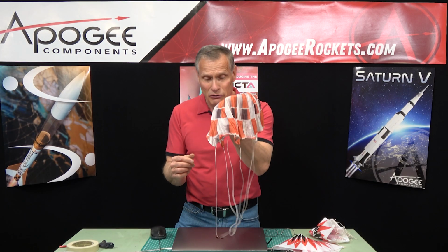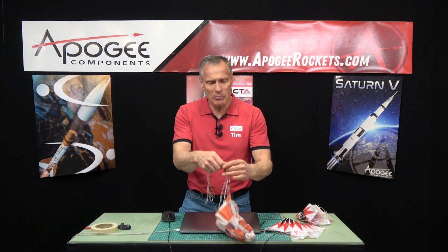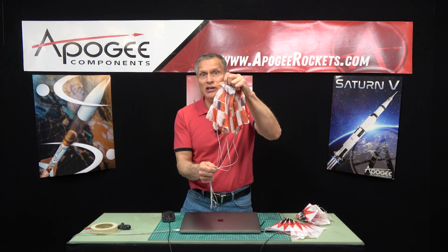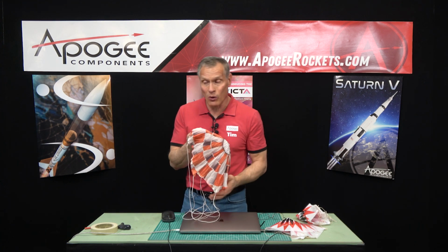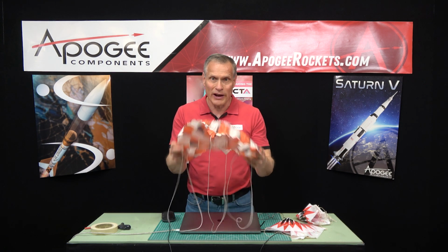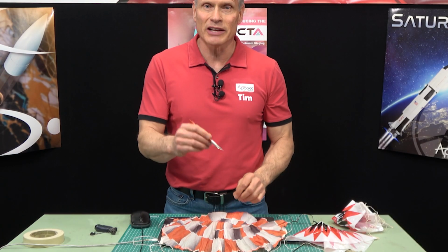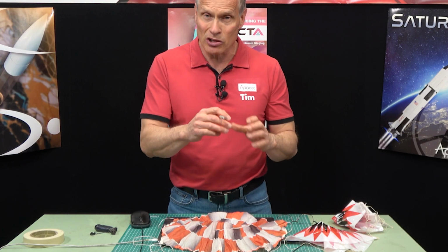You don't typically want to cut a hole in a nylon parachute because they're a little bit more expensive and they're nicer. So reefing that parachute with a piece of tape could be one way to reduce the area so that your rocket falls faster. And if you do want to cut a hole in a nylon parachute, what I recommend is to take your hobby knife and a heat source, like a little butane lighter, and heat up the blade so it's nice and hot. And when you cut into the nylon, it's actually going to melt the nylon cloth